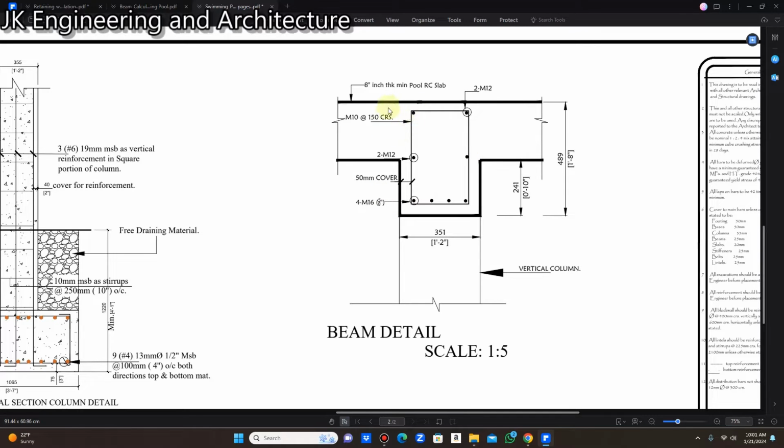Now the shear reinforcement. For the shear reinforcement I use 3/8 bar at 6 inches on center, because when I did the shear calculation, the shear was pretty high, and I think I was getting something like 10 inches on center. But because the weight of the water on the column and the beams is going to be constant, I decided to decrease it from 8 or 10 inches down to 6 inches, just to be sure.